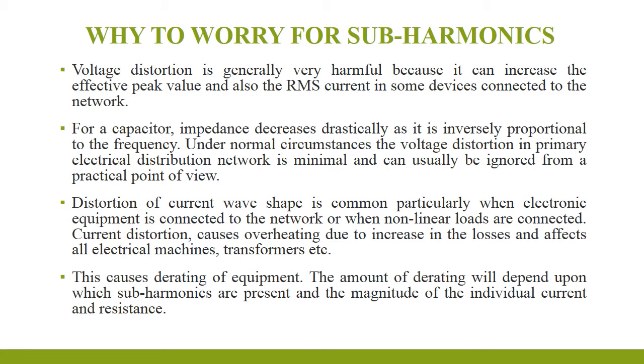Under normal circumstances, the voltage distortion in the primary electrical distribution network is minimal and can usually be ignored from a practical point of view. Distortion of current wave shape is common, particularly when electronic equipment is connected to the network or when non-linear loads are connected.